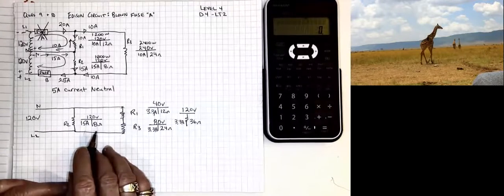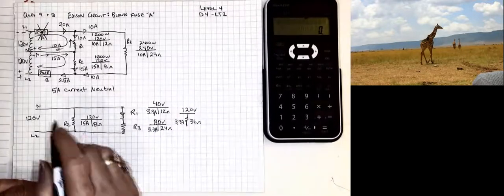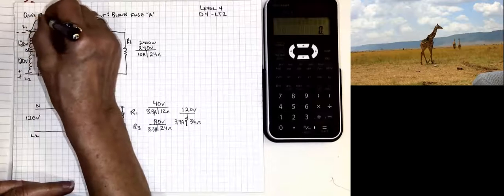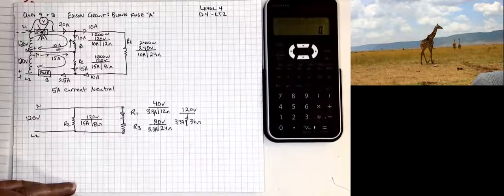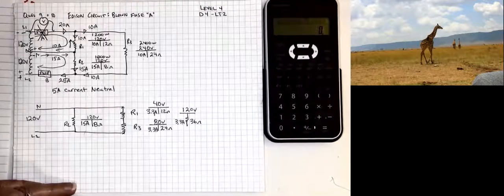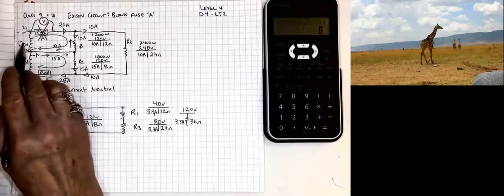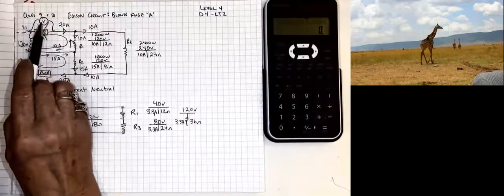Now, what I have to figure out is what's actually happening, and what would happen if I put a voltmeter across this fuse. How much would the voltmeter read? And the tricky part is that I can use Kirchhoff's voltage law, which says the algebraic sum around any closed loop has to equal 0. So if I look at this closed loop, it's being closed by the voltmeter.